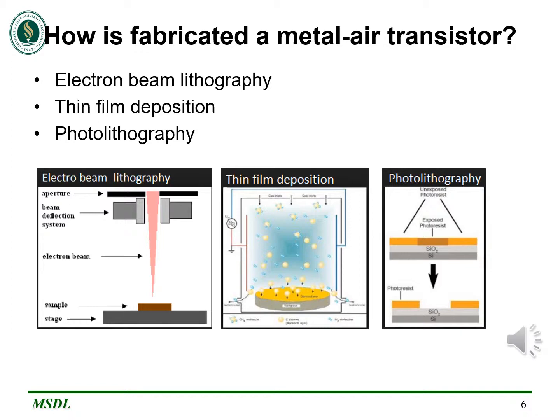To achieve maximum resolution, subsequently, exposed patterns were developed in methyl isobutyl ketone mixed with isopropanol in a 1:3 volume ratio. The samples now had nanogaps defined. On this structure, a 50 nanometer thin metal film, tungsten, gold, or platinum for different sample sets, was deposited. To aid adhesion, a 5 nanometer titanium layer was utilized.